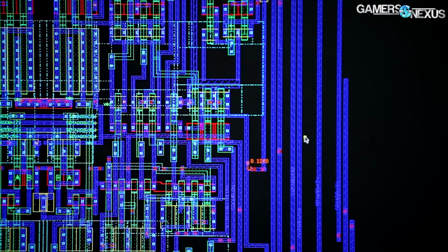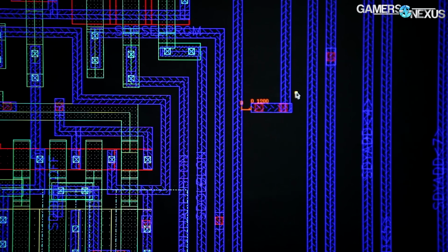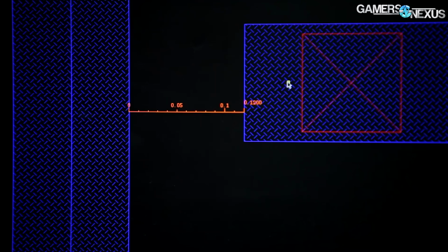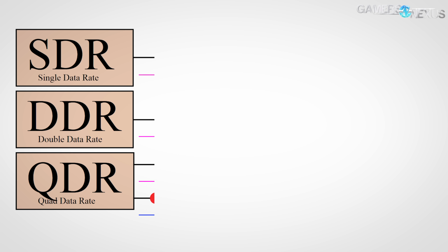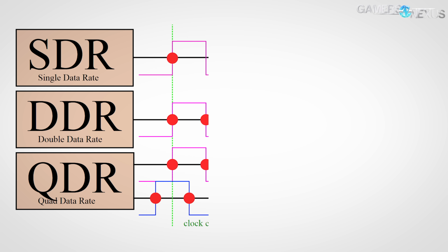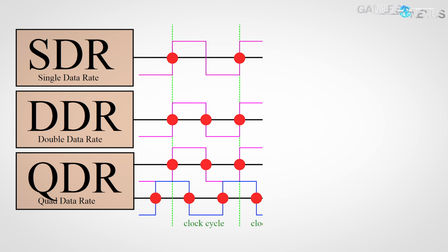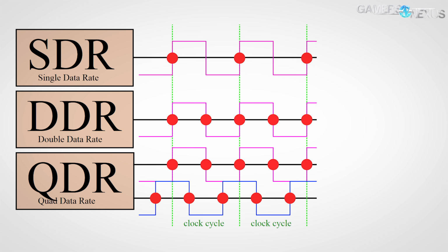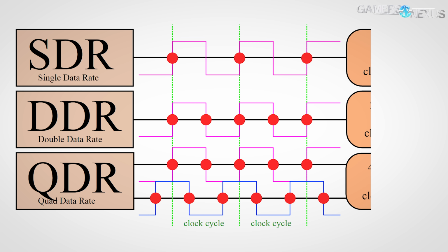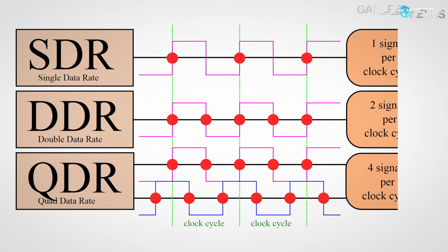First, the basics. While memory frequency is measured in hertz, or cycles per second, the unit for memory timings is just plain cycles. To convert clock cycles to a measurement of time requires knowing the frequency of the memory. This is listed in megahertz, or units of 1 million hertz. 3200 megahertz has a clock frequency of 3.2 billion cycles per second, so the time for a cycle to complete should be 1 over 3.2 billion seconds.